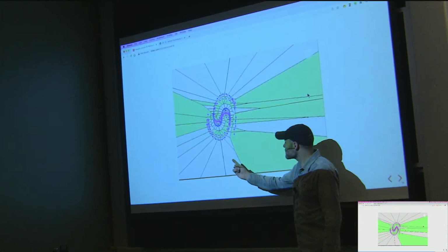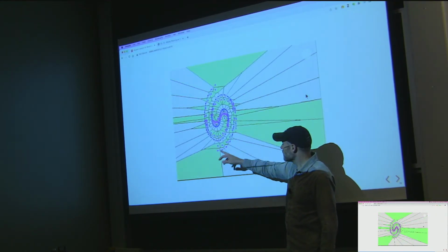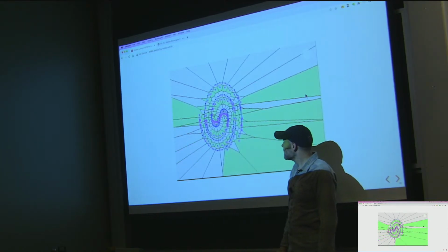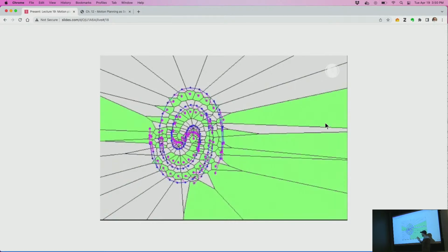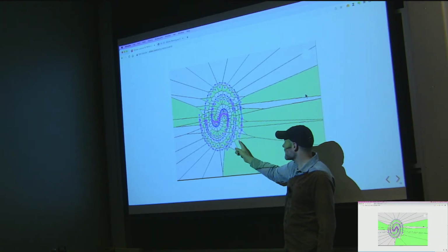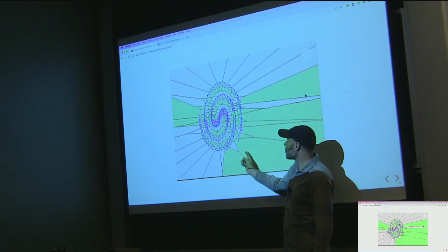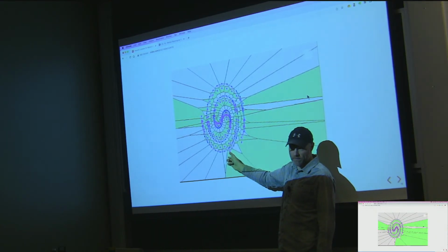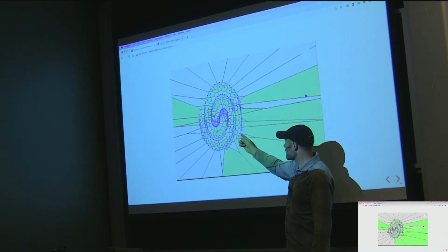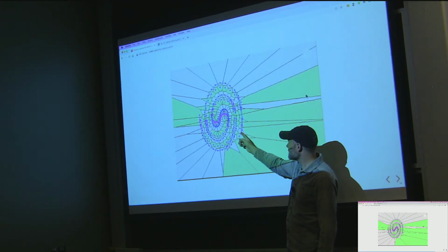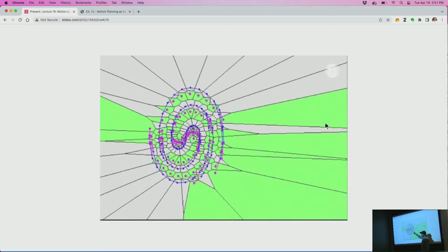So in this particular version of the algorithm, a reachable set was approximated just by a handful of points. And the algorithm goes like this. It says, pick a point at random. If the closest point is a reachable point, which is one of these pink points, and the green boxes here are the Voronoi regions associated with the reachable points, then I'm going to go back to the point that it was obtained from, and I'll expand that node. Every time I expand a node, I'll fire out a few more pink points.